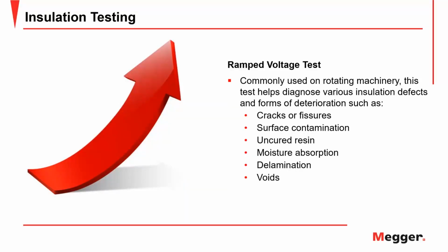And this is a pretty sophisticated test, and before you apply this, you really should read some literature on it, and I can provide you with that. I have a couple articles, so let me know if you're interested. It's more sophisticated than a step voltage because you can actually get information out of it regarding the actual nature of the problem in your insulation and where it may be. Next.